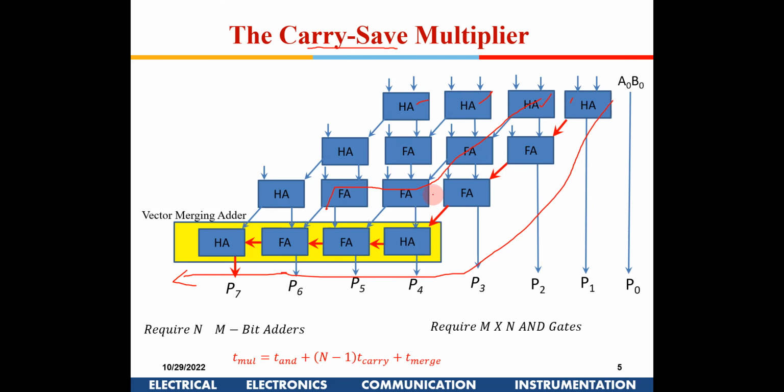So what I can do is I can use these as a normal low speed adder, ripple carry adder, whatever I have, right? I can just concentrate on these three elements, and also I can use carry look ahead adders and all we saw, right? So this entire 4-bit adder I can use a fast adder out here. So I don't have to optimize every particular block out here, right? So that is the advantage.